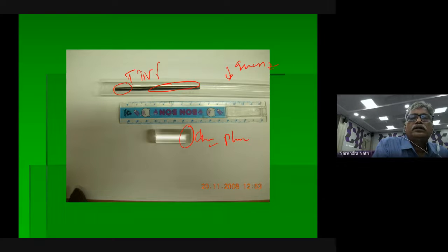So here you place it inside. This is actually the rod I placed. If you want, you can put a plate also, if you have a big quartz tube. Before placing, you have to get a vacuum inside. The tube chamber area you connect to a vacuum pump and suck out all the atmospheric air. Then you place it.